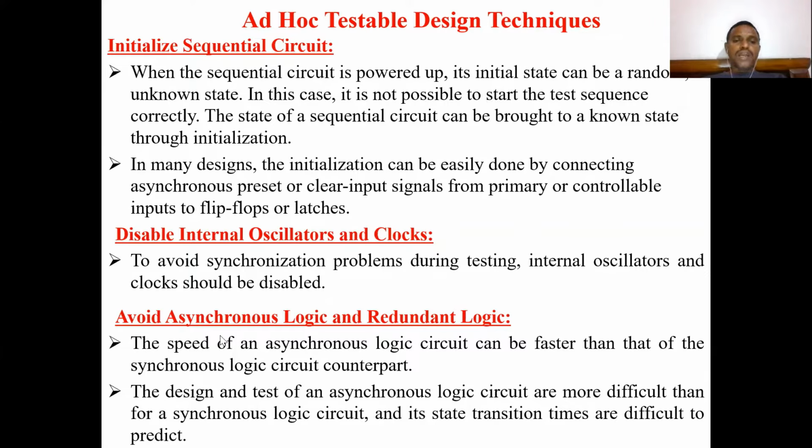The next one is to avoid asynchronous logic and redundant logic. If you compare synchronous and asynchronous circuits, the speed of an asynchronous logic circuit can be faster than that of its synchronous counterpart. However, the design and test of an asynchronous logic circuit is more difficult as compared with a synchronous logic circuit, and its state transition times are difficult to predict. As we saw for a sequential circuit, the initial state is not predictable. Similarly, we have the same problem here with asynchronous logic circuits.